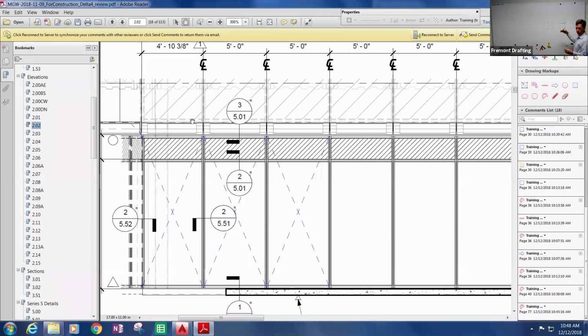Usually it's a floor by maybe a bay wide that's moving as a big mass, and there are still joints between each other. So this element is just moving back and forth. That's what translating is. It could be any shape, really. It could be like this, but if it's just moving left to right horizontally, that's translating.